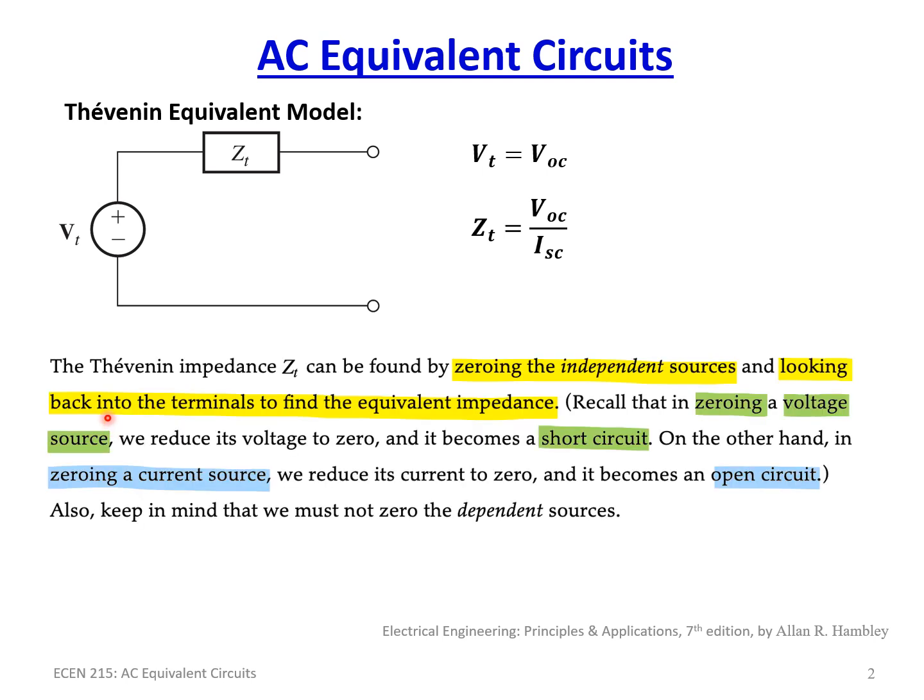So just to confirm everything here, the Thevenin impedance ZT can be found by, again, using the zeroing method. And that is where we zero out the independent sources. That means that if you have a voltage supply, zeroing it out means it becomes a short. So if we had an actual circuit here instead of the Thevenin, the power supply would be a short. If it was a current supply, it becomes an open. So that model still works. It works completely well. It just now, instead of computing the equivalent resistance of the circuit once you've done the zeroing, you would now compute the equivalent impedance. So ZEQ instead of REQ. So everything stays exactly the same process.